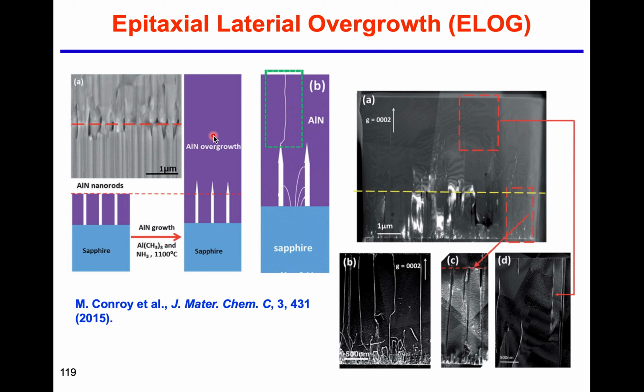And the gallium nitride growth is very, very interesting. Typically, for conventional growth, we need to have a lower mismatch, and once we form some dislocation, the dislocation will continue. But for gallium nitride, that's very interesting. If we introduce some dislocation first, actually this dislocation will not continue. Okay? So that is what we call epitaxial lateral overgrowth.